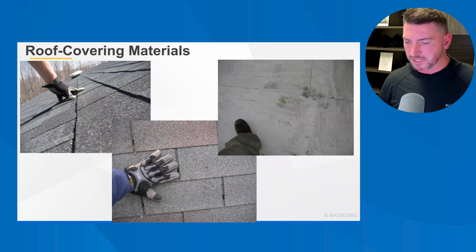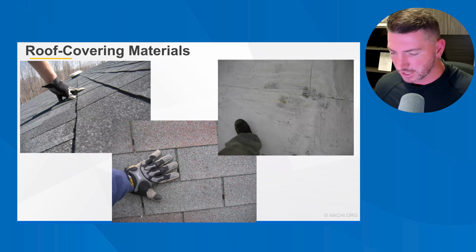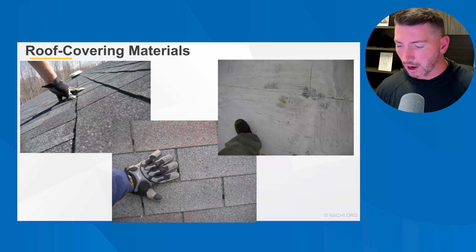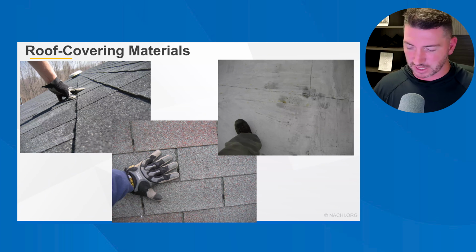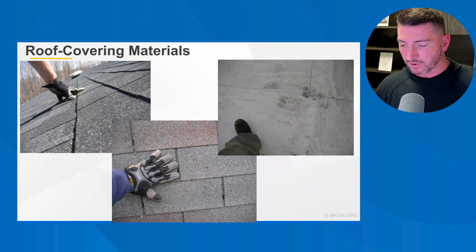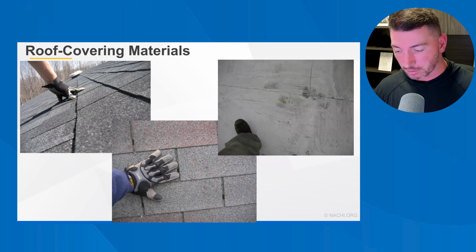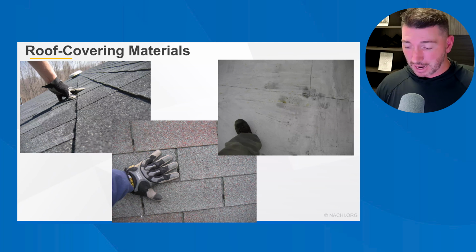Roof covering is a term specifically used and defined in the International Residential Code and building standards. Roof covering is the covering applied to the roof deck for weather resistance, fire classification, and or appearance. And since the roof covering is layered, not all of the roof covering material is visible during a home inspection. There are other terms that refer to the combination of components used together to form a complete assembly. A system is made up of smaller parts. An assembly is made up of smaller components. And most of the parts and components are not readily visible. They are beyond the scope of a home inspection.